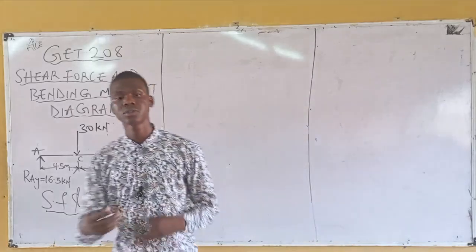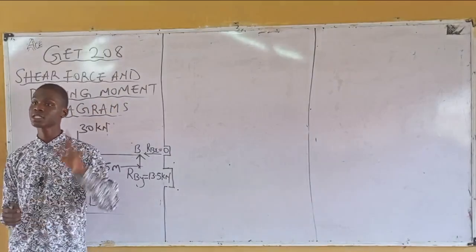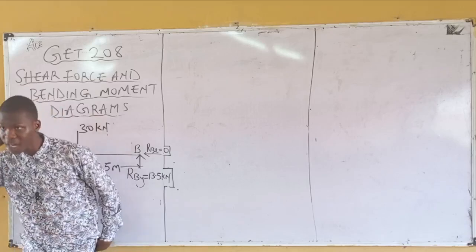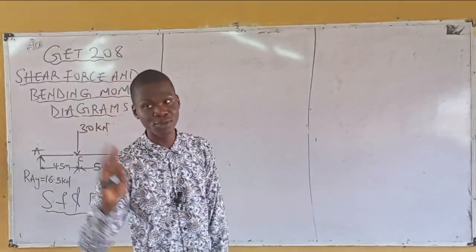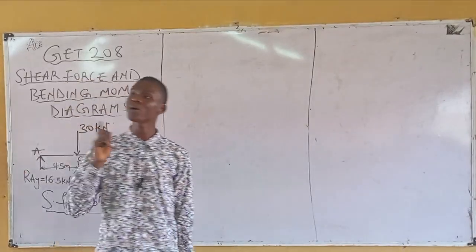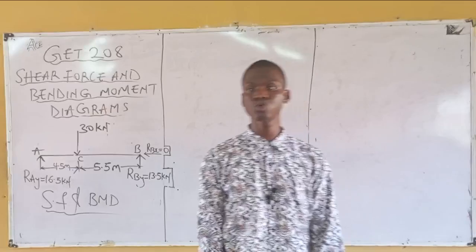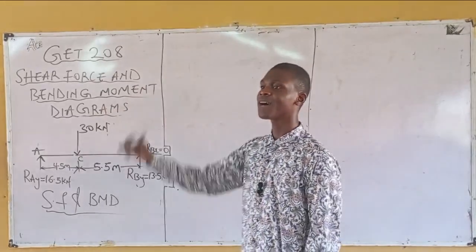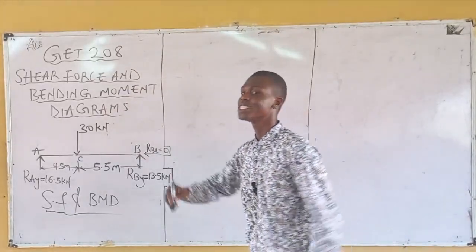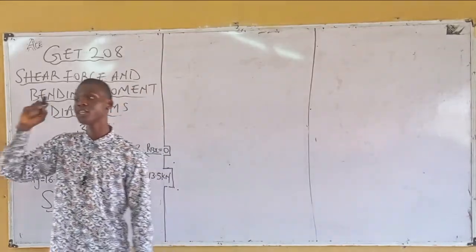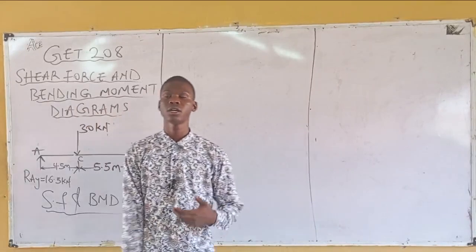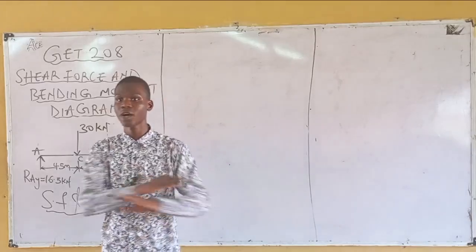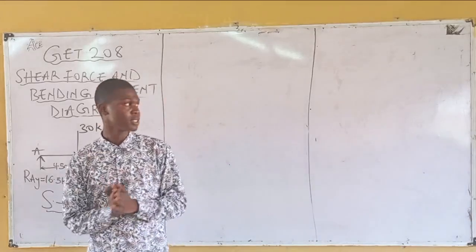But probably you see how that one also works, right? Then that's number 1 when calculating shear force. Number 2, shear force value must end with 0. As far as this level is concerned, shear force value must end with 0. In some cases, it is not necessarily the case that it ends with 0, but as far as this level is concerned, shear force value must end with 0, right?